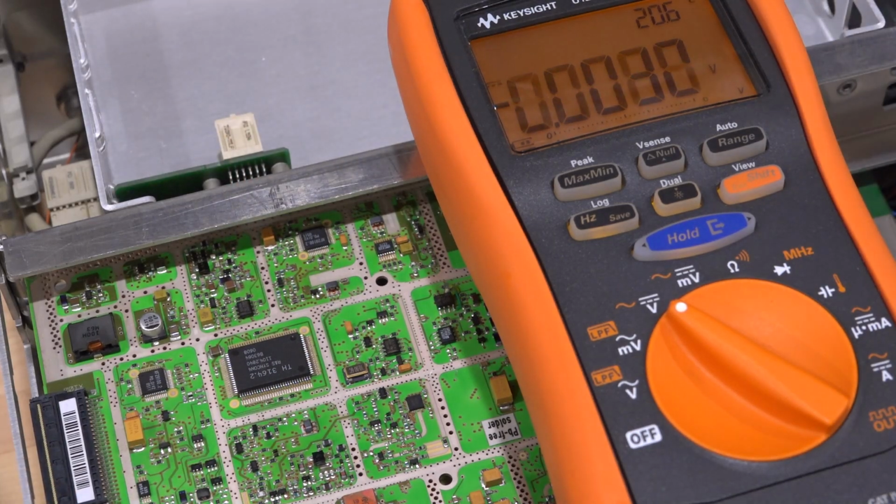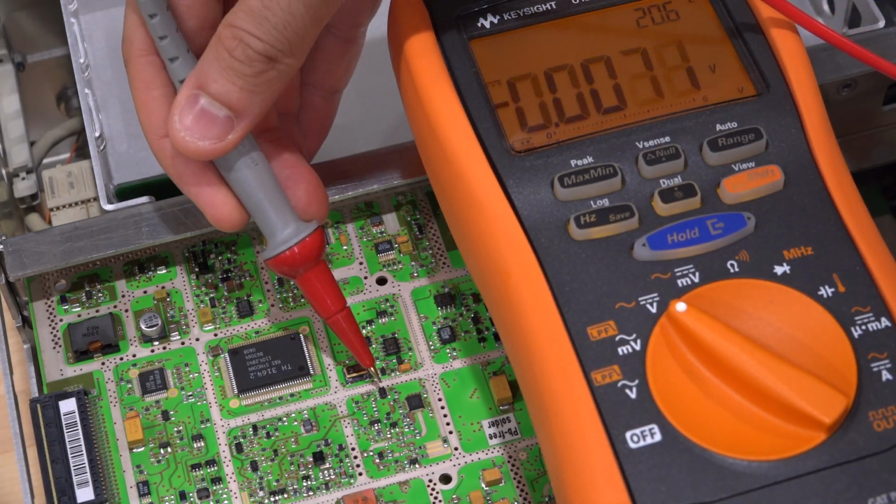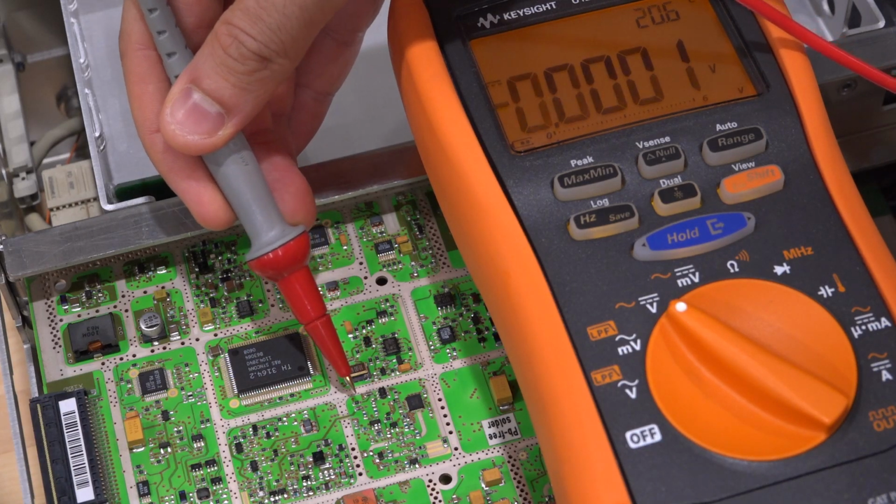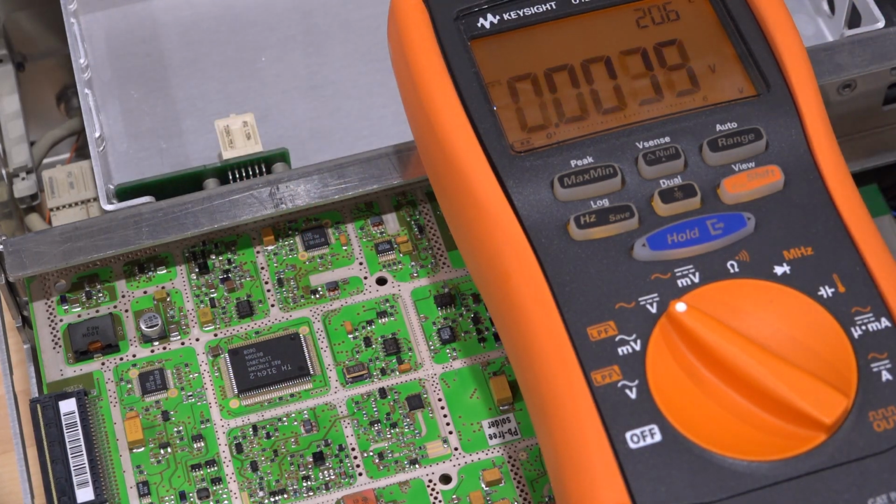Obviously, that's not due to current, because you're going to have an enormous amount of current through a 1 ohm resistor to make that kind of voltage drop, and that resistor would be on fire. So is the resistor bad? But then why would the resistor go bad? The reason I'm worried, and I still think the divide by 4 may be the fault, is because this 1 ohm resistor is typically used like a fuse, basically.